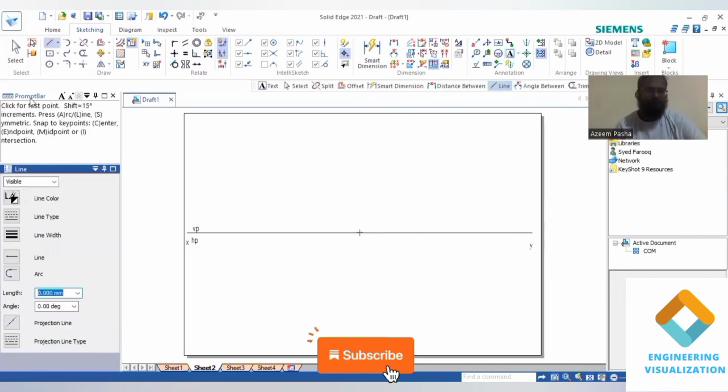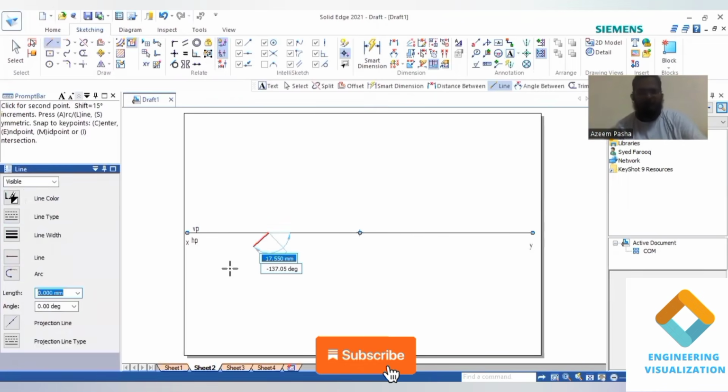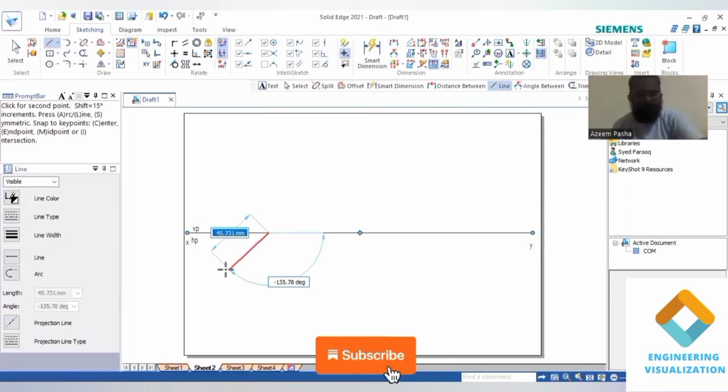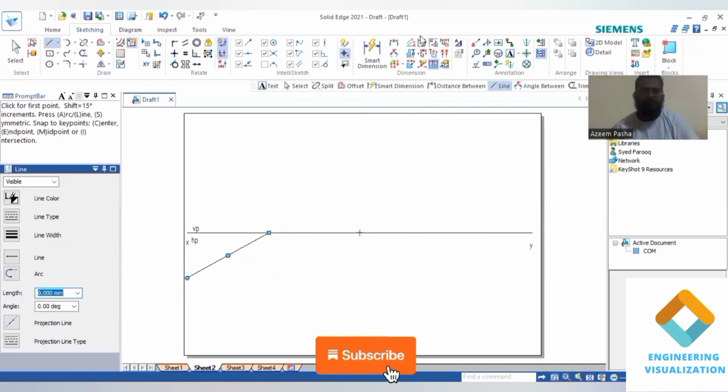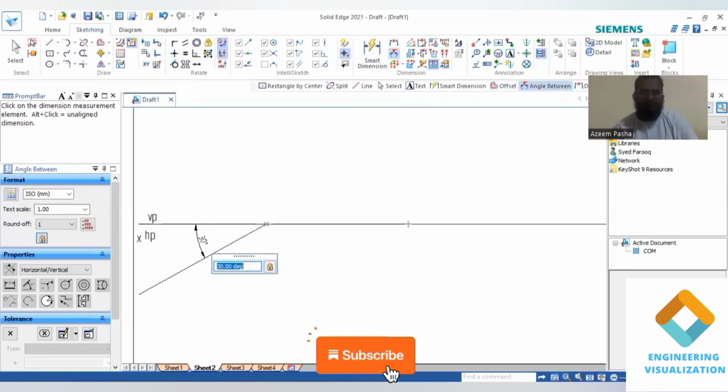Now you draw an angle line. Here you should draw an angle line for 30 degree. So 30 degree means below the XY line you should give an angle of minus 150. If you give 150, the angle you get here is 30 degree. You can measure the angle by using the angle between command, so you will get the angle 30 degree.